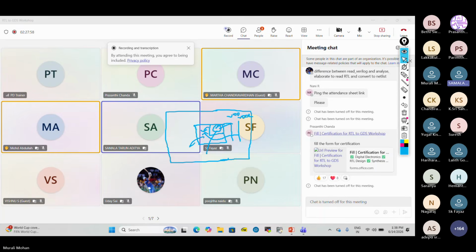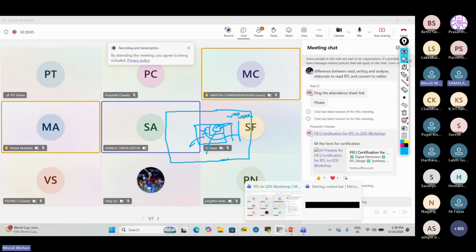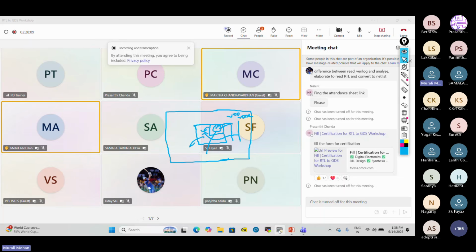My doubt is, for the entire design, there will be common rails only, no, sir? Common rails, stripes, rails also you can specify for the particular domains. Yes, you can create more than one rail also.